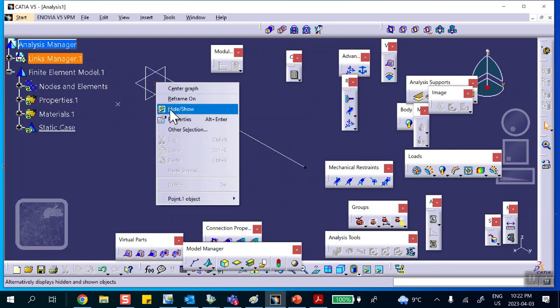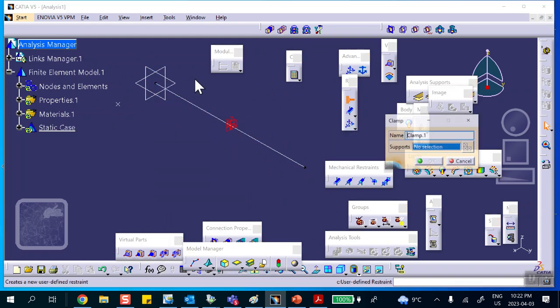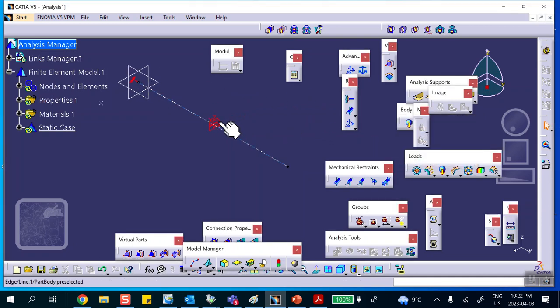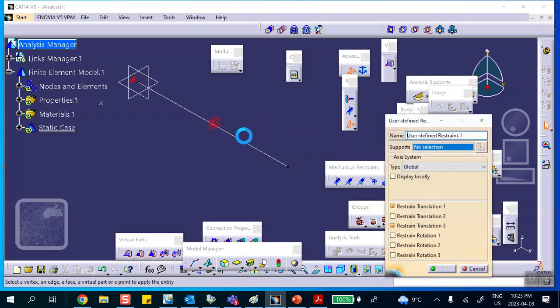One end is clamped, so this end is clamped. And because I want to do a transverse vibration here, let me take all of these points, this entire line, and say it does not move in the direction x. This basically takes out any out-of-plane motion and will prevent that. Nothing will move out of the YZ plane.